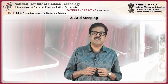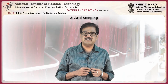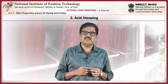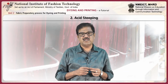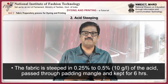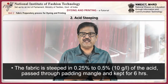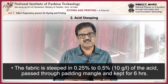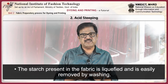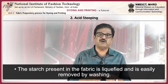Acid stripping. In the acid stripping method, dilute hydrochloric acid or sulfuric acid or a mixture of both are used to hydrolyze the starch from the sized fabric. The fabric is steeped in 0.25 to 0.5 percent or 10 grams per liter of the acid, passed through a padding mangle and kept for 6 hours. The temperature rises to 50 degrees Celsius. The starch present in the fabric is liquefied and is easily removed by washing.